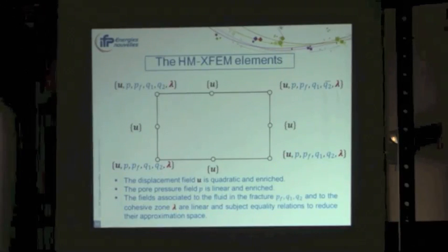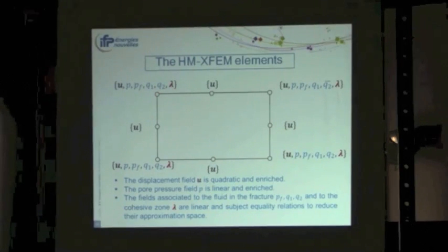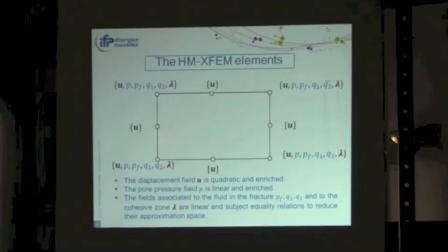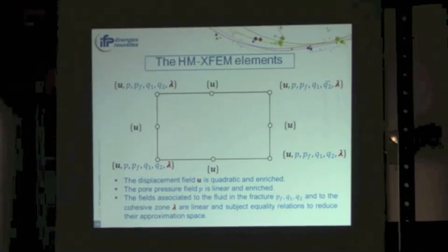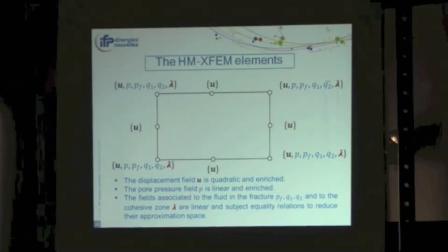Here is an HM-XFEM element. So as you see, the summit node carries all the degrees of freedom, so the displacements U, that are also carried by the middle node. So the displacement field is quadratic and enriched. By enriched, I mean that it is an XFEM field, so it can be discontinuous over the fractures. And the summit node also carries all the other quantities, so the pore pressure in the matrix, the pressure of the fluid in the fracture, the fluxes, and the Lagrange multiplier lambda, which is associated to the cohesive law.